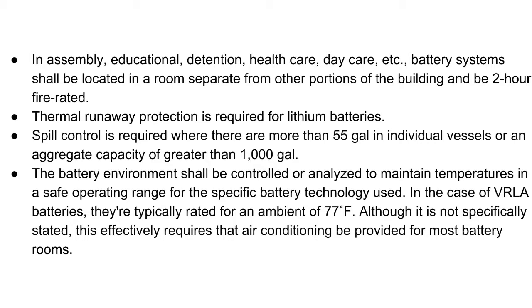There are some firewall rating requirements for rooms where there are kids. Temperature sensors are also required on the batteries. So a lot of the IFC and the NFPA requirements are similar to each other. The battery environment shall be controlled to maintain temperatures in a safe operating range for the specific battery used.